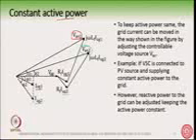But what is happening with respect to the grid current? Here you see that I am keeping the projection of IA on the x axis, or on the VAG axis, the same under both these conditions. What does this mean? It means that VAG into IA into cos phi is constant. So the active power delivered by the voltage source converter remains the same for both IAG1 and IAG2. For both these currents, the active power delivered to the grid remains the same.